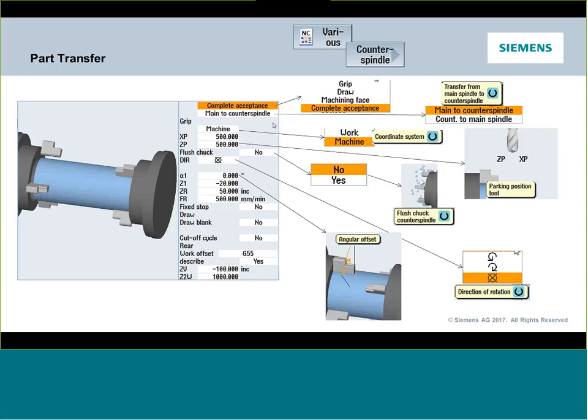So that's just a simple yes or no scenario. Now, when you get down to direction, this is what do you want the spindles to be doing during the transfer. So you got a couple options. You can have the spindles at off, so it should just come over with both spindles in a stop state, grab the part, and then bring it out, and then she'll fire up on the next operation.